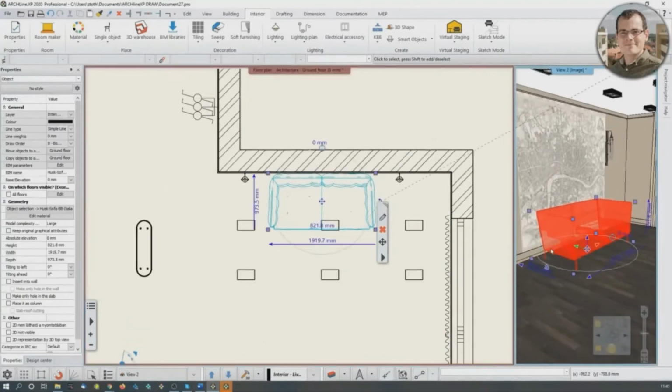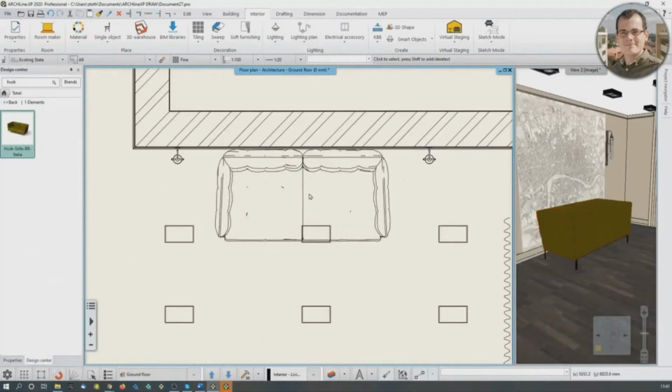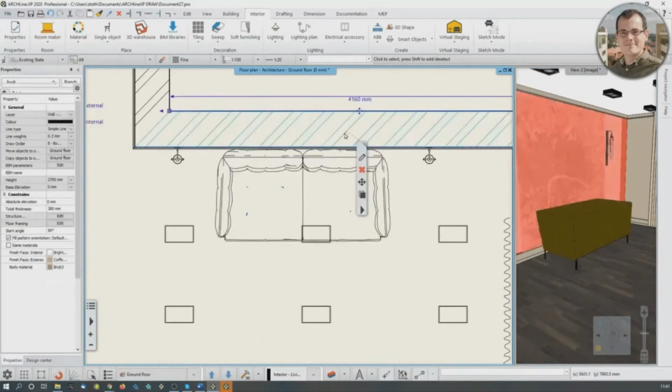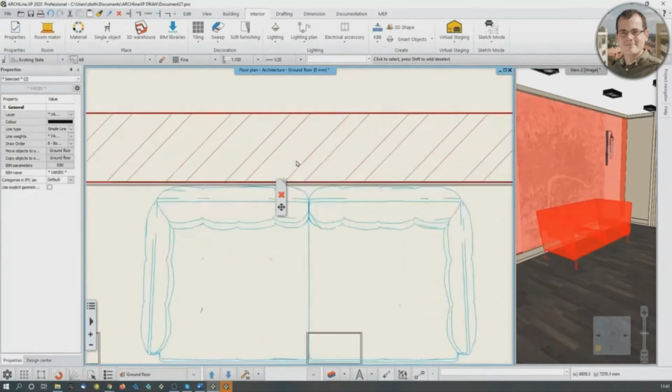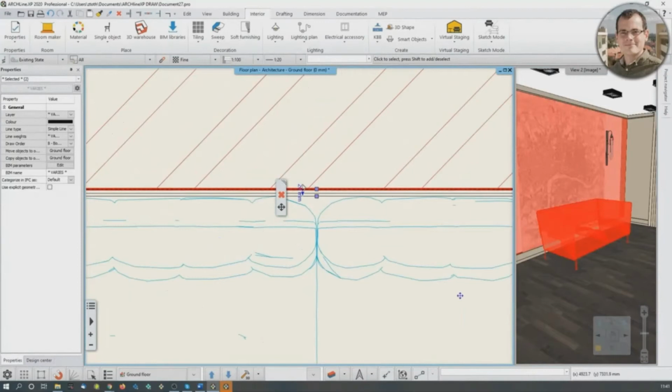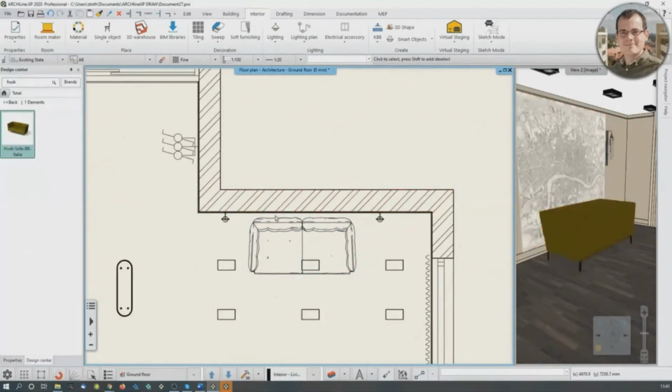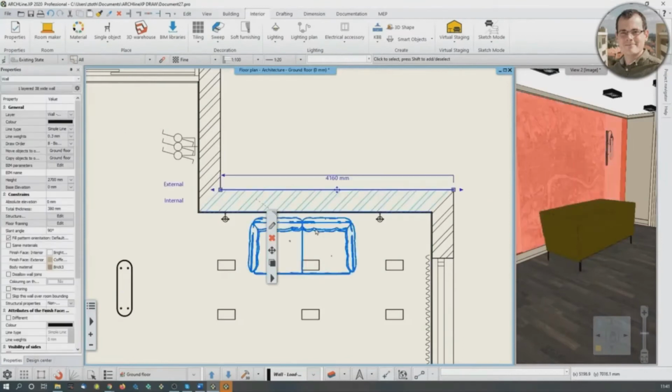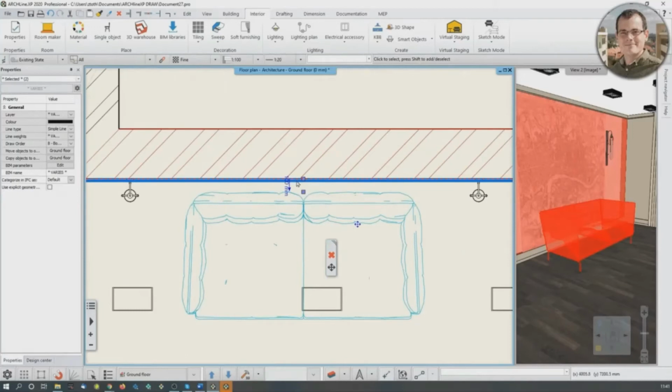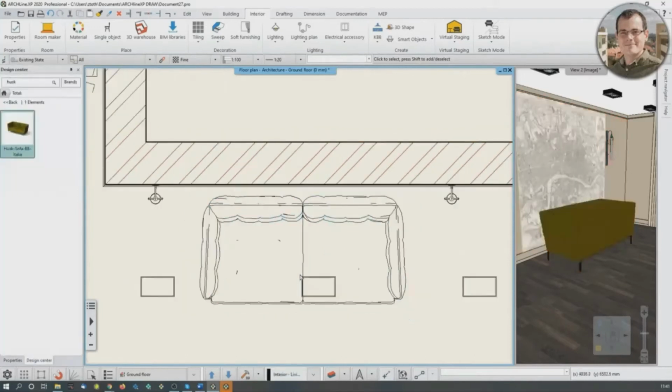Okay, this is not good. Let's say that I'm a cat person, which I'm not, but let's assume that I am. I want to have some kind of gap between the sofa and the wall so the cat would be able to go through. So I'm just going to click the wall, and holding the Control key, click this sofa. Now the software tells me that currently there's only a 2 centimeter gap between the two elements. If I click on this marker, I can say I want it to have 100 millimeters. That way you can move things, or distance things from each other. So again, click on one element, click on the other one while holding the Control key, and then you can control how far things are from each other.